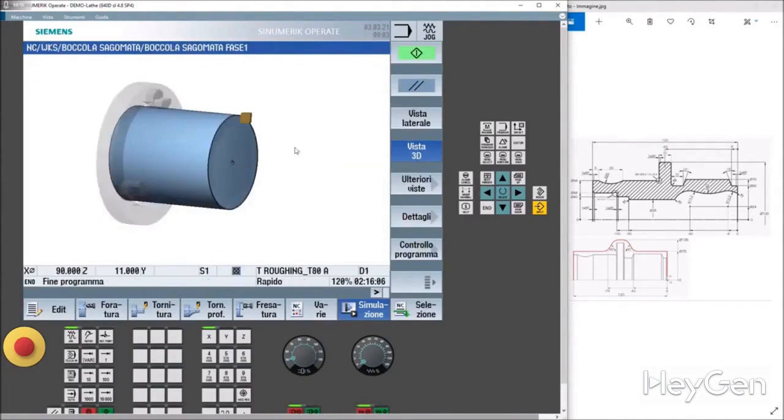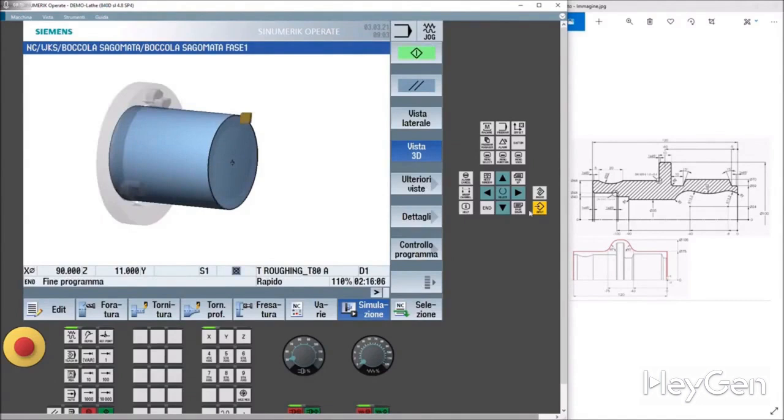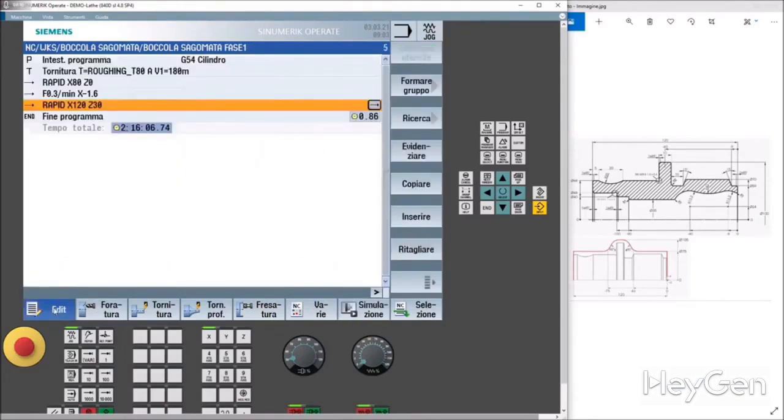You see the tool is starting to work. I checked the program, it was a bit too fast. The tool starts working from here. Why? Because I defined a rough stock of 105. Actually, the rough stock is 75, I lean on 80 and go down. This shouldn't be a problem for you because you know that the graphics right now are quote-unquote misleading. Let's go back to editing. And we continue with our little project.